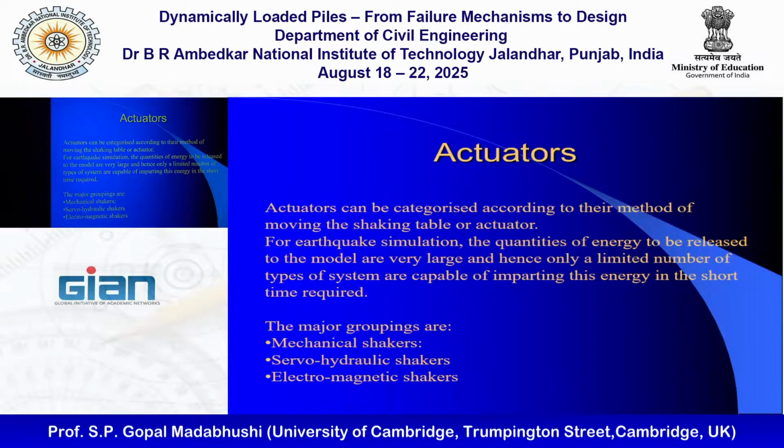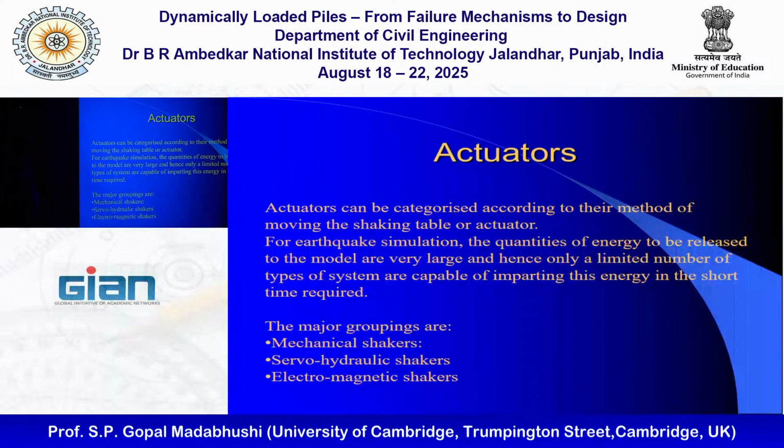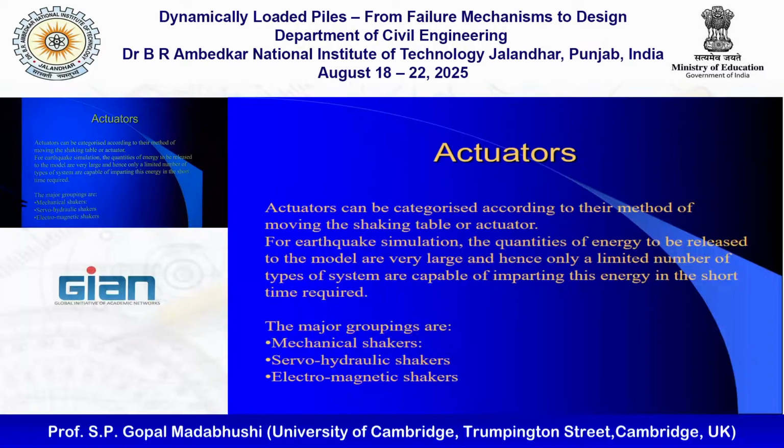Typically, what are available at the moment, I put here, mechanical actuators. I built a couple of those. Servo-hydraulic shaker, that's the one we are using in Cambridge and elsewhere in the world as well. And this is the one we are trying to build for IIT Bombay at the moment. You can also have electromagnetic shakers. Only Japanese have one or two of those.